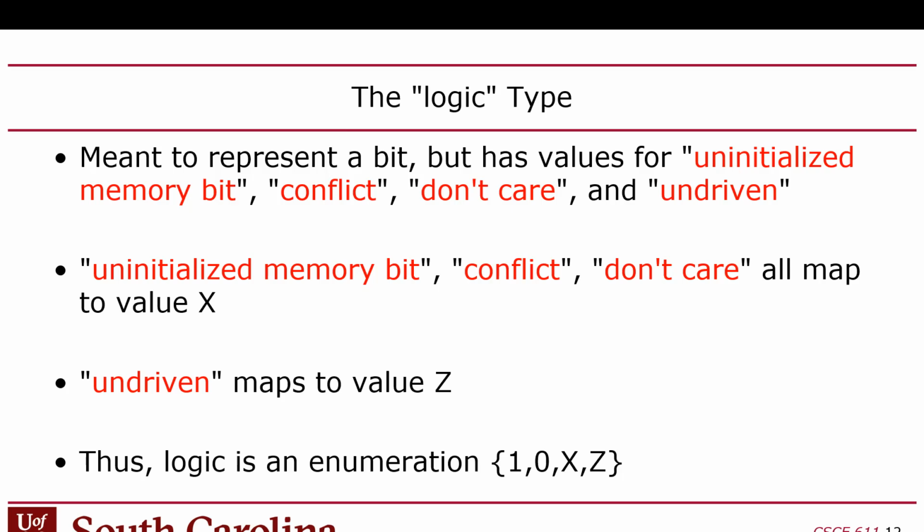Basically, in a digital logic design, you would expect every value to be binary, right? Because that's the whole point: you're designing a digital logic circuit, and digital means binary, 0 or 1, or true or false, or high or low, or asserted or not asserted. But there are additional values that these signals can take on when you simulate an HDL design.